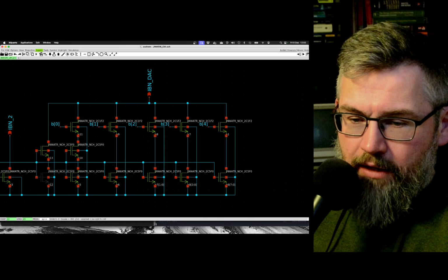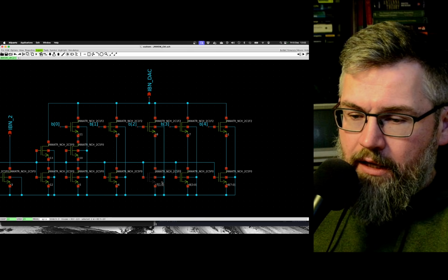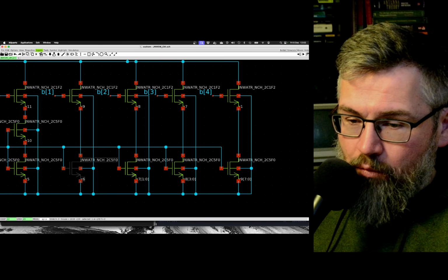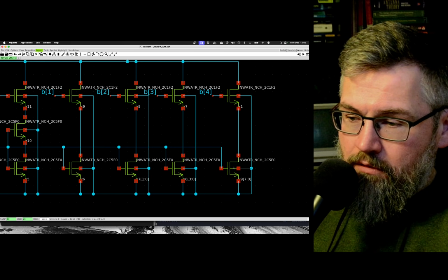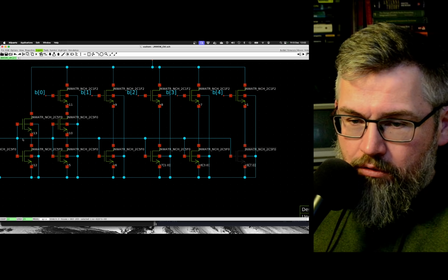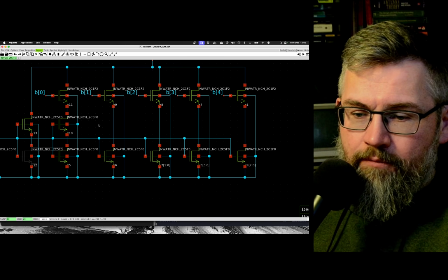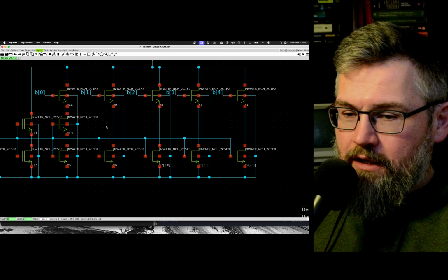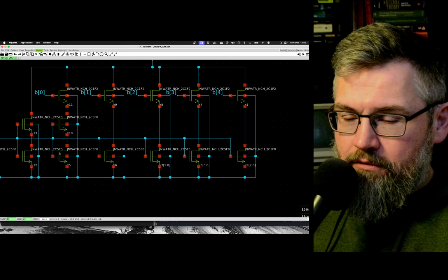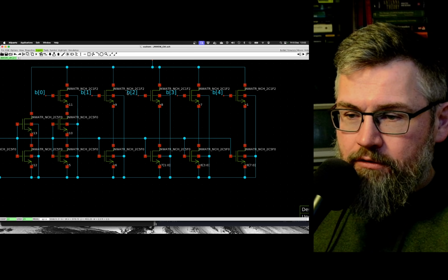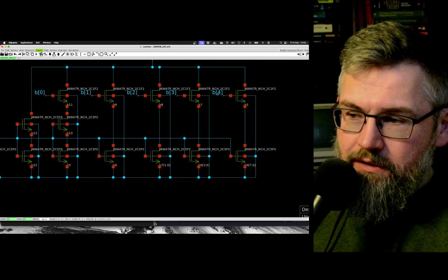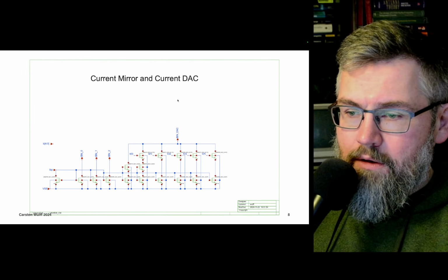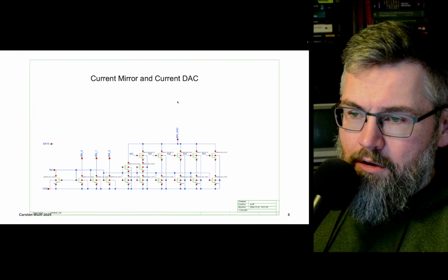It basically has the same NMOS current mirror outputs, but we can see that here the number of units has changed. So here we have 1, 2, 4, 8. And on the first couple of units, it actually is 2 transistors in series, so that it's not entirely half, but roughly half. And for each of the binary scaled transistors, we have a switch that is controlled by a digital signal. So this is the one we want to sweep and then see how the output current changes.